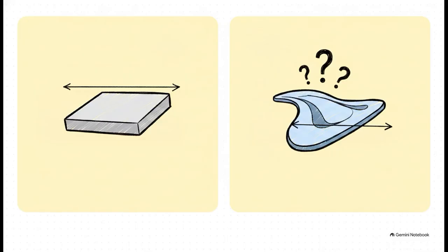Check this out. It's a bit of a pattern interrupt. On one side, we've got a traditional, simple, flat part profile callout. It just controls a few distinct reference points. But on the other side, we have a full freeform surface with a profile tolerance wrapping the entire model. And here is the kicker. It is the exact same symbol on the drawing. No way, right? But the freeform application is controlling orders of magnitude more geometry at once.